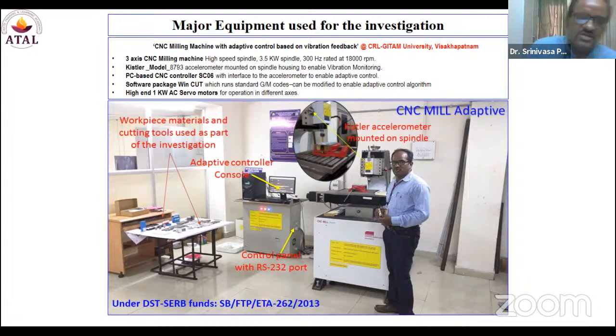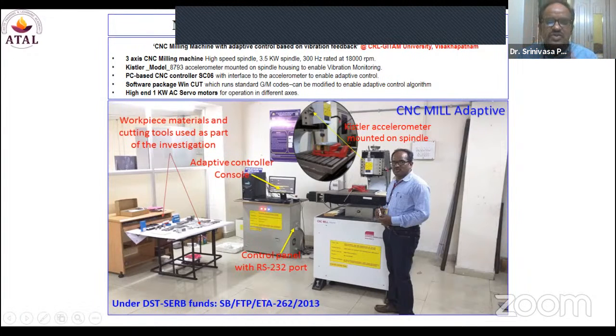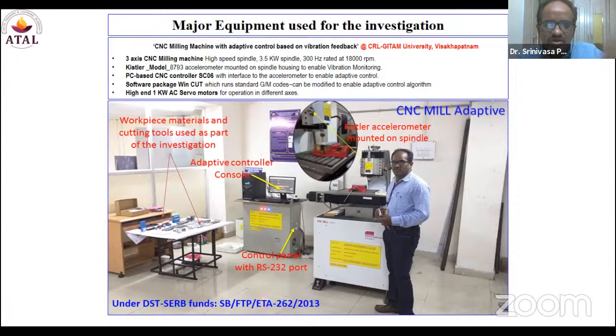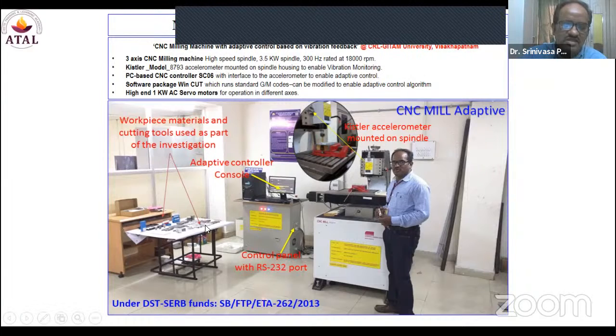Here the important task is to establish communication between the sensor, CNC machine controller, and the VFD drive. They must work under common control and common programming control. That particular program is developed with MATLAB. As long as they work effectively, the results will be very good. To explore this research, we have considered 3 different workpiece materials, 2 different cutting tools, and 2 different diameters of the cutting tools.